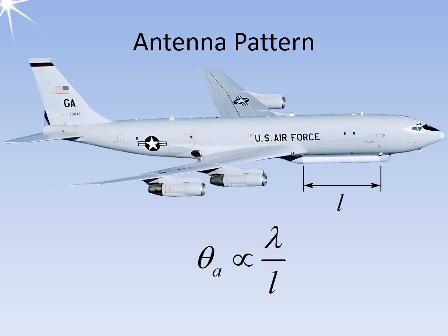For different types of antenna, this ratio can be easily multiplied by an empirically determined factor. For practical reasons, the antenna length cannot be increased indefinitely, so a side-looking radar with a real aperture is only suitable for low altitudes where the distance between the antenna and the terrain is not too large.